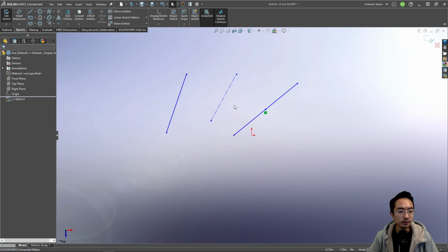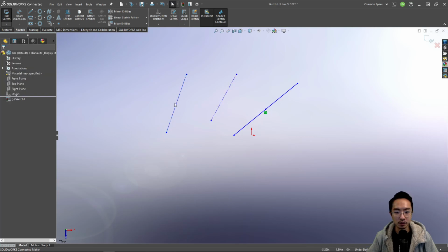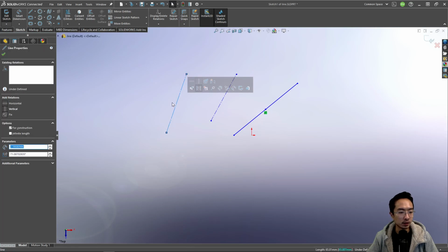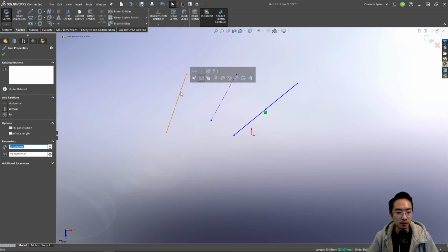At different times you may want to use the three types. So in here, if you click line, you could also change a normal line into a line for construction. So now these two lines are pretty much the same. They're both like dash lines. So here you could click it.